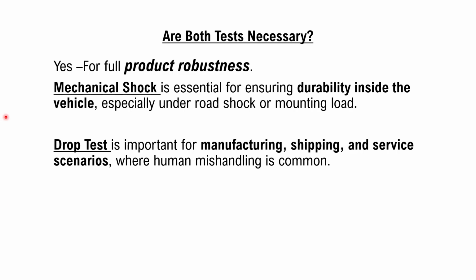Now, our question is, are both these tests necessary? The answer is yes, for full product robustness. Mechanical shock is essential for ensuring durability inside the vehicle, especially under road shock or mounting load. Whereas drop test is important for manufacturing, shipping, and service scenarios where human mishandling is quite common.